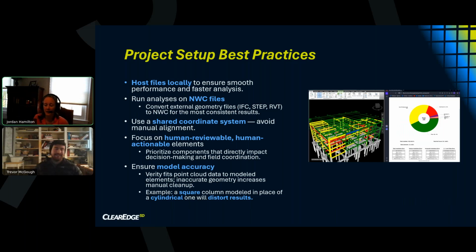The more accurately the shape of your model geometry is representing the true shape that is going to be collected in the point cloud, the more correctly Verity will be able to find you your true as-built fit by being able to more easily match the points that we're seeing to the geometry that's modeled. Yep. And there is some wiggle room, like for example, a pipe hanger. If it's modeled, say, 6 inches, but scan data shows it's like a foot, then Verity can say, hey, it's found. But yeah, if there are some pretty significant discrepancies,